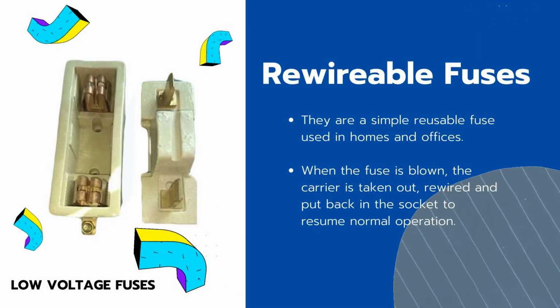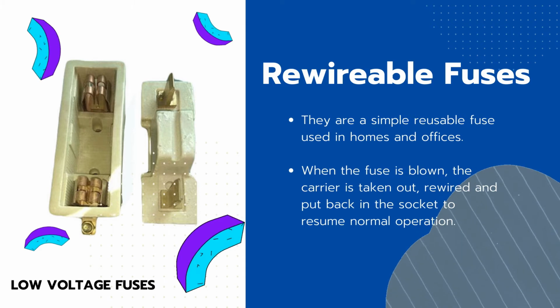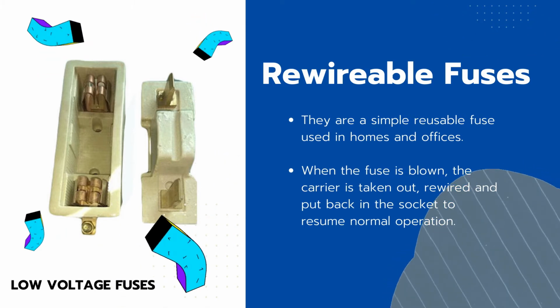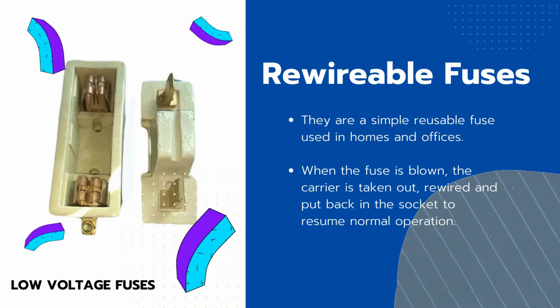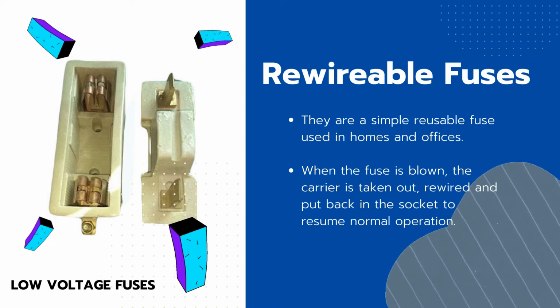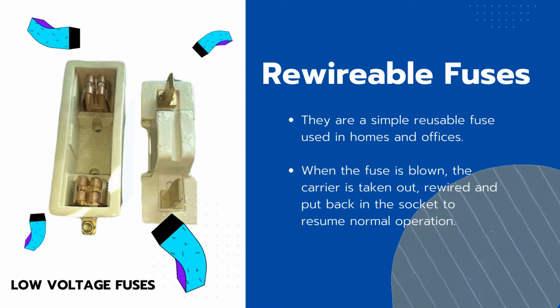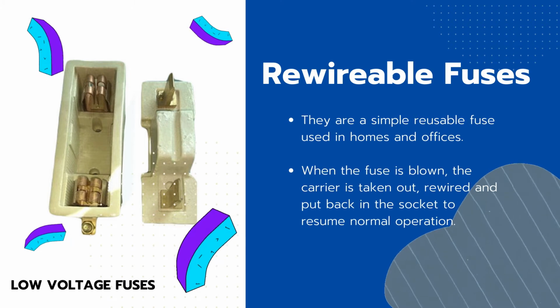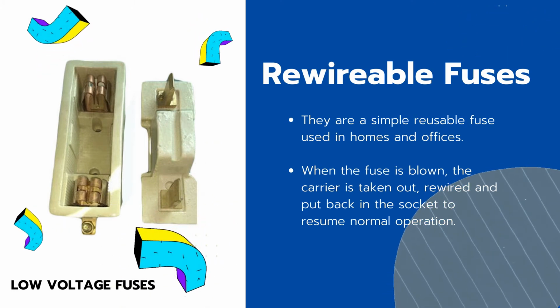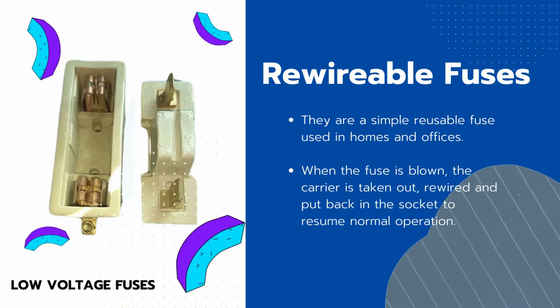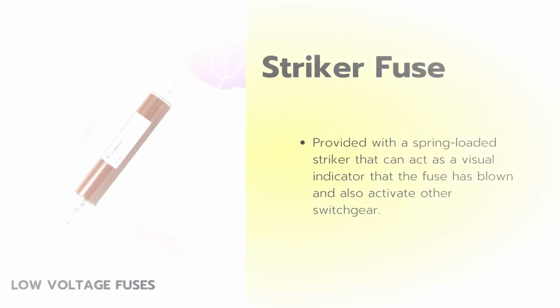Rewirable fuses. They are simply reusable fuses in homes and offices. They consist of a carrier and a socket. When the fuse is blown, the carrier is taken out, rewired, and put back into the socket to resume normal operation. They are somewhat less reliable than HRC fuses.